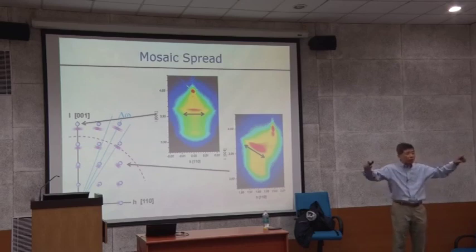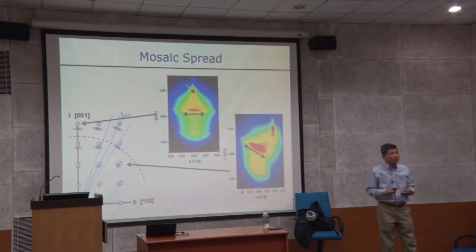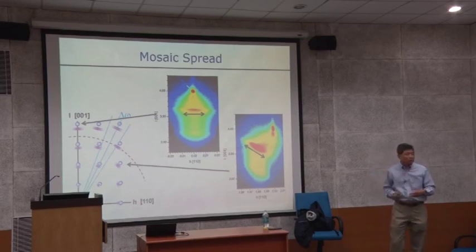So your X-ray is with this direction. L scan along this is basically the 2 theta angle. So your X-ray diffraction is only one-dimensional information. One-dimensional information is very limited information about your sample. So you want to get three-dimensional information. Basically, that is what you want. Your structure is three-dimensional information. In order to get that information, you need this kind of reciprocal space understanding.